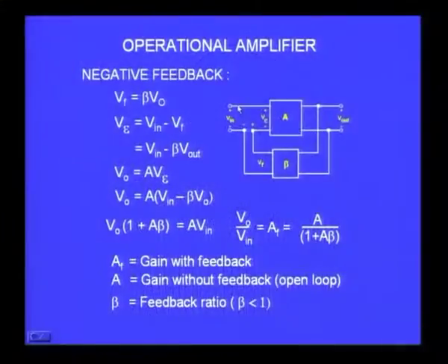I have here on the screen an amplifier with a gain A without any feedback. You have an input terminal, you have the output terminal. Then what we do is take the output terminal in parallel and connect to a network here. B is another box with a network there, which is a fraction, beta is a fraction. So a fraction of the output voltage will be taken, which is called Vf, the feedback voltage, and that is given in opposition to the input voltage.